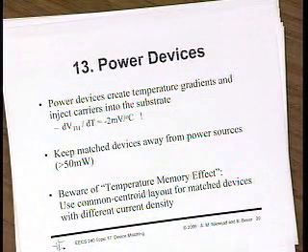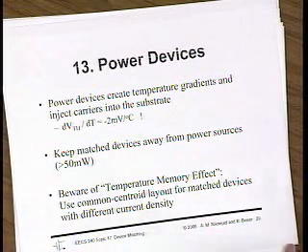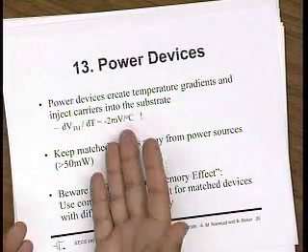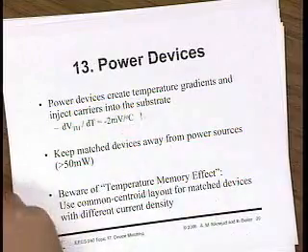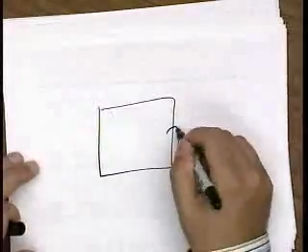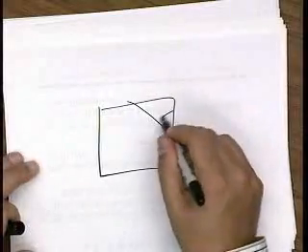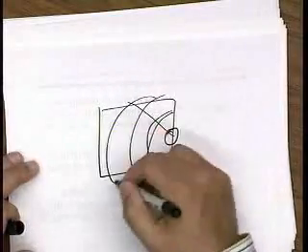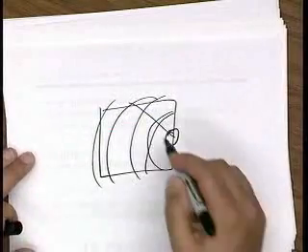the temperature drops. So if you're designing matched transistors, make sure that first of all you use techniques like common centroid, but sometimes using common centroid is cumbersome. The parasitics of putting everything in a common centroid outweighs the benefits. Well, if you know that your device is here in your layout, so this is the power transistor, you can probably guess that the thermal coefficient is going to look something like that.